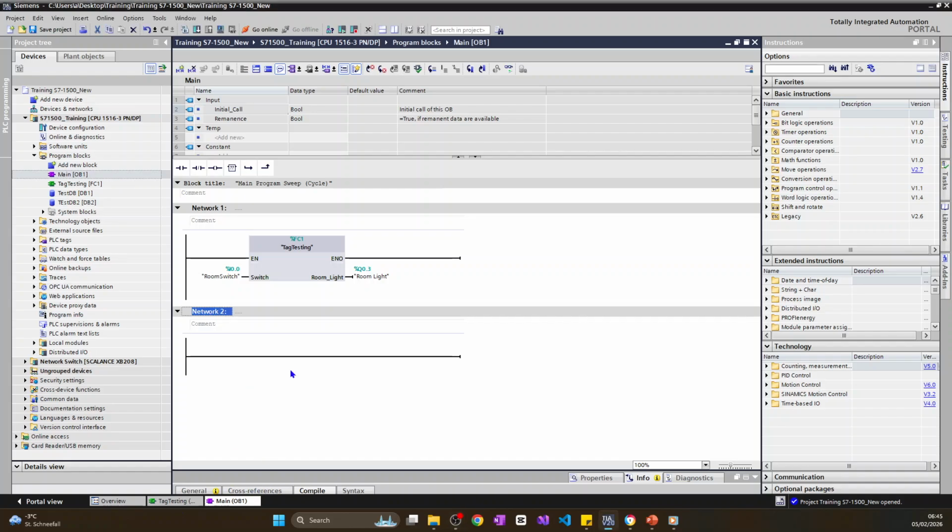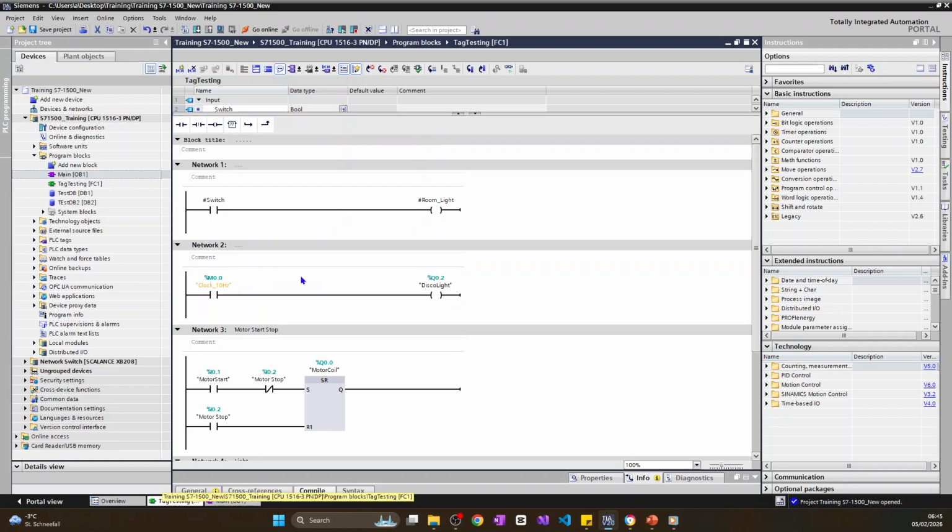So ladder logic, which looks very similar to relay logic, you can directly see how the code is done. This is a normally open switch. This is a coil, and this is usually how you would wire this in a PLC, right? In a PLC panel. And that's how we do ladder logic.